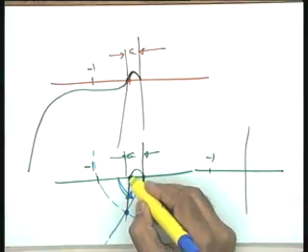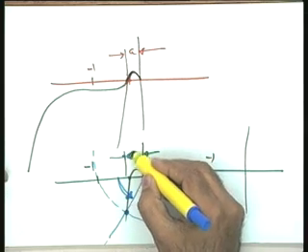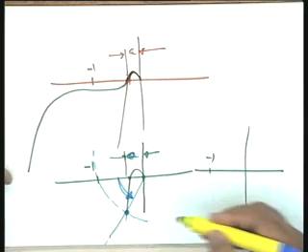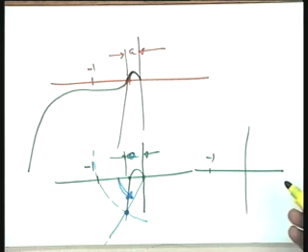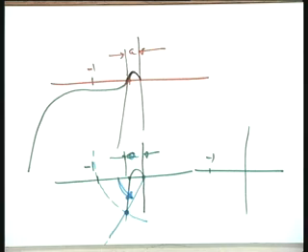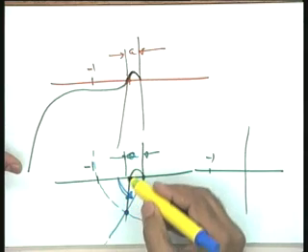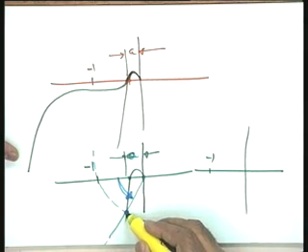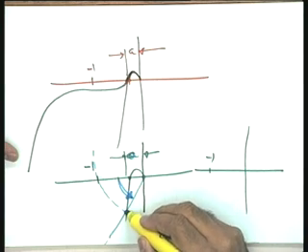So, if I consider this very plot which I have given you, where there is an intersection over here, in that particular case you find that this distance and this angle, the two, you can claim that even these two may not be sufficient. So, naturally the complete plot is a better description of its distance with respect to the minus 1 plus j 0 point. But if I take the complete plot, I cannot set the complete plot suitably into my design algorithm. After all, I want a simple design algorithm. Therefore, the complete plot has been quantified into two indices. One is the intersection with this axis, and the other is this particular angle where the magnitude is 1.